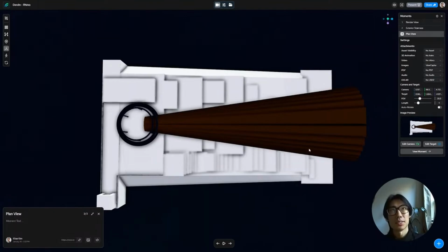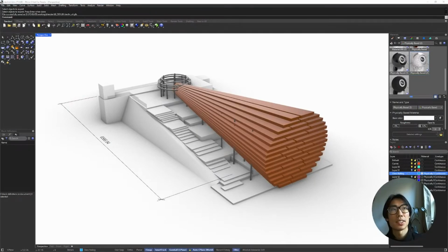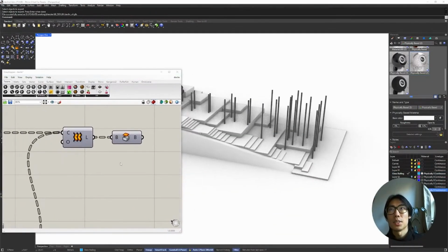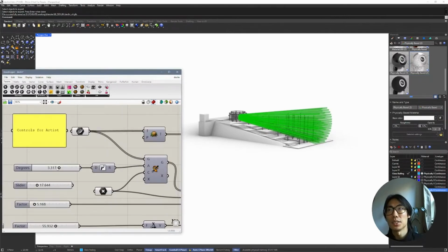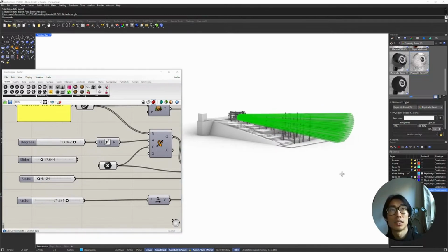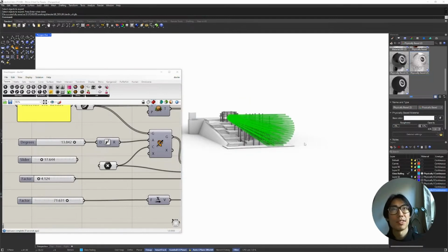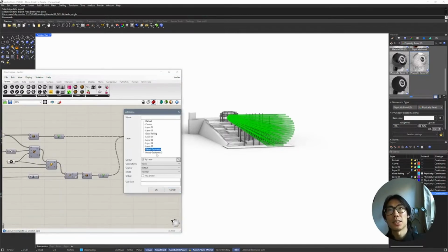And Foveate is designed to be highly iterative, right? So we have this model, but what happens if you go back here, you're working with your artist, and all of a sudden, they hated that design. So you could go back to our Grasshopper script, and this is part of the reason why Grasshopper is so great. What they actually want to do is change the design to be much more tilted and, let's say, smaller. And they want it to extend out further. So here someone is able to very quickly change the design without needing to model again at all. And then you can simply create a new layer called Baked Geometry 2, and rebake this geometry and do a second design iteration.